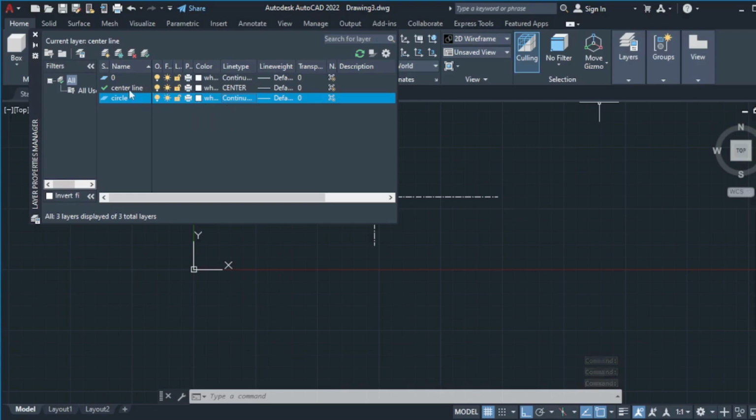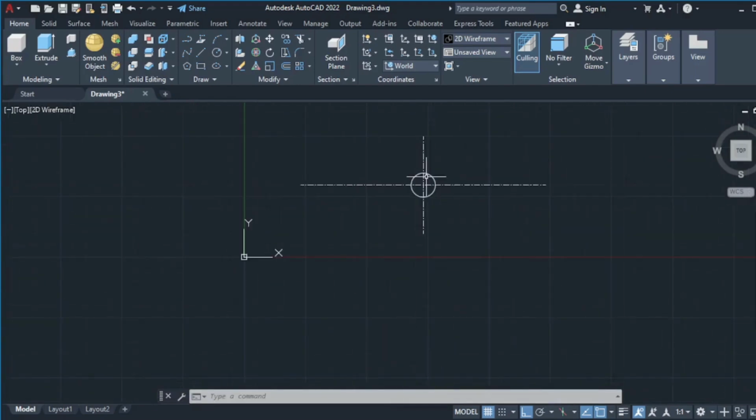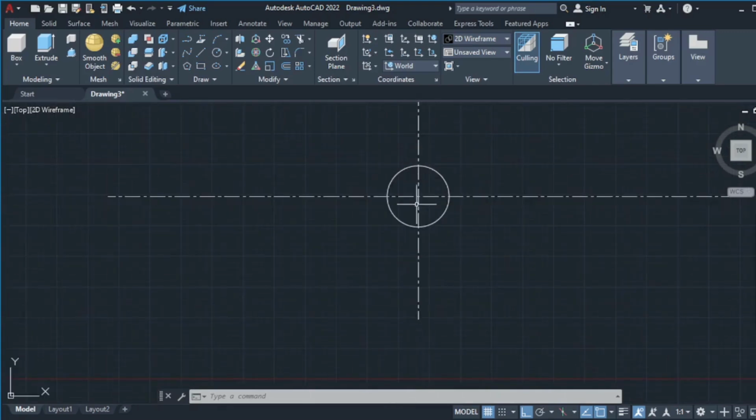But once you work with that line, we'll make sure it is marked. Then you left click twice here, then you cancel it. Then now circle, the midpoint, the radius is 2.5. Then you click on enter. Then we've made a circle with radius 2.5.